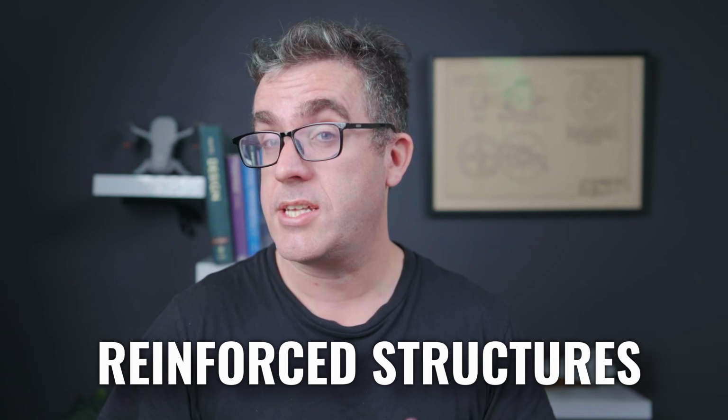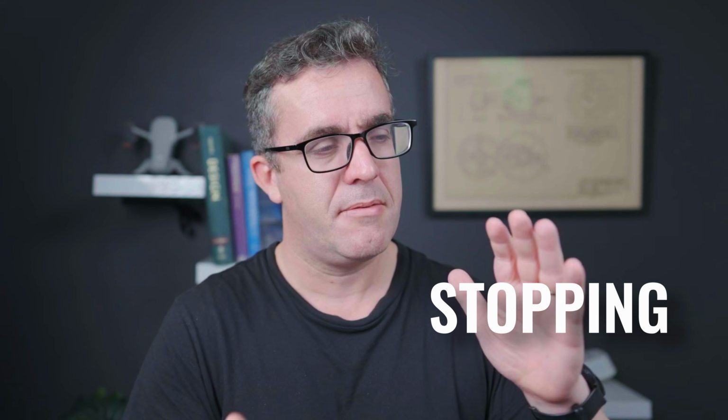So the way you deal with this, typically in reinforced structures, is to have vertical lines of support through there. Now it's not as efficient as if you went on an angle, because you can see the direction of the crack, but it's a lot harder to reinforce as you don't fundamentally know necessarily which direction the crack's going to go. It's just about stopping that plane from occurring.